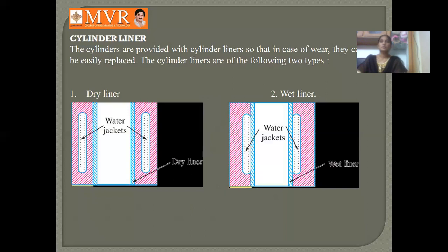Compare the values of Zn by P, and then we will find the coefficient of friction. After the coefficient of friction, we consider the heat generated and heat dissipated in the bearing. From the heat generated and heat dissipated, we will find the artificial cooling required for the bearing. This is the simple procedure of the journal bearing, and we have also discussed the simple procedure of the ball bearing. What is the procedure of a ball bearing?